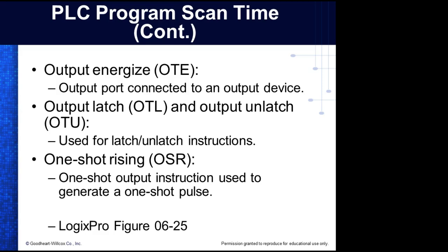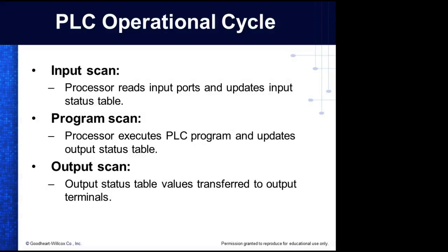So this creates one shot per scan, and it'll go true, and then it'll go false until the next scan. They have reasons for them. We used to use them to create a certain timed pulse every time it would be activated. So you get one pulse, but you didn't want it to stay true. Hard to explain, I know. That's okay. I've learned enough.